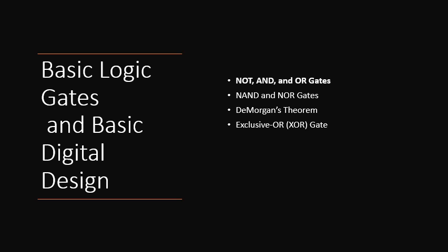Then we will focus on exclusive OR, known as the XOR gate. Then we will discuss the multiple input gates other than the standard two input gates for the normal gate operation, or one input for the NOT operation. We will see how multiple inputs are handled by these logical gates. And then we will discuss the logic gate ICs which you used for your lab experiments, that are the 74 series ICs. Mostly, the ICs we utilize for your lab work to design basic digital circuits are the 74 series.